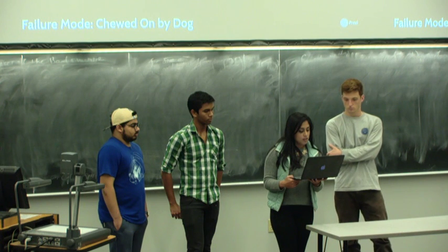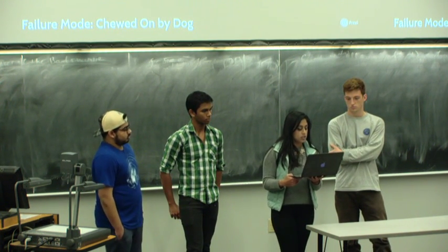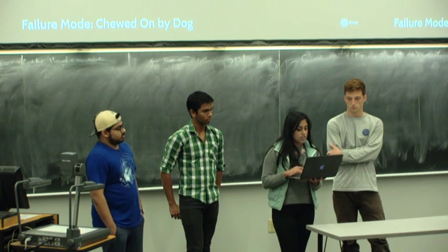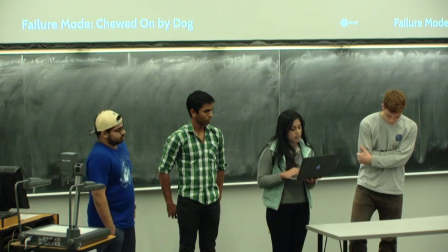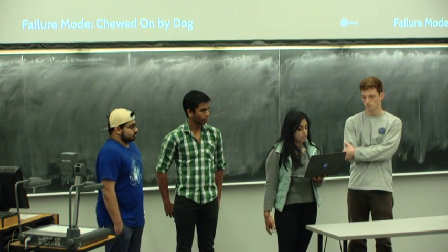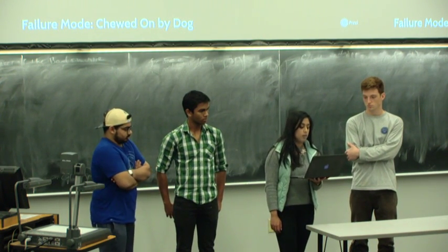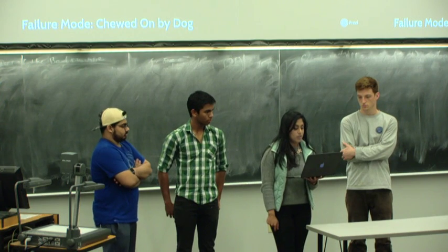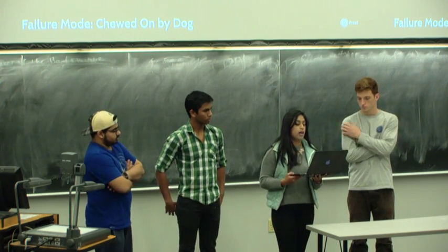And then the potential cause or mechanism of failure, we said that it's a materials inspection failure. We said that its occurrence would probably be a 1. Hopefully that doesn't happen often. Current process controls, again, it's operator training and instructions failure. The detection, we gave it a 3, and so the total RPN was a 30. Because the occurrence is probably very low, we didn't recommend an action for this either.